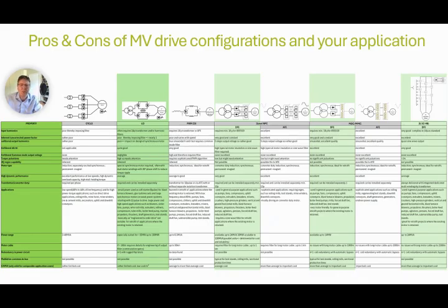The performance of the drive relates for the most part to the application requirements. The Cycloconverter performs quite well at low speeds with high dynamic overload capacity. In load commutated inverter applications, high performance is generally not required, and the relatively low performance of this drive is therefore not an issue. The dynamic response of voltage source inverters ranges from good to excellent, and components like reactors in the CSI do not limit them. PWM CSI offer superior performance, overcoming some drawbacks of natural commutated, load commutated and cycloconverter fed drives.